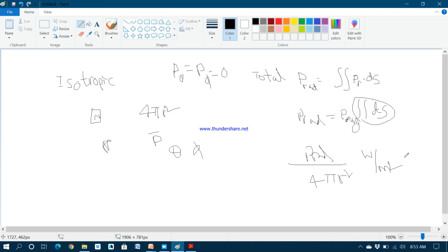This is one of the important characteristics of the isotropic radiator. The average power in an isotropic radiator is nothing but P radiated by 4 pi r square. Whenever in future sections you want to calculate any parameters, power or something else, this is our reference. P average, the average power radiated, equals P radiated by 4 pi r square. So this is one of the sessions.